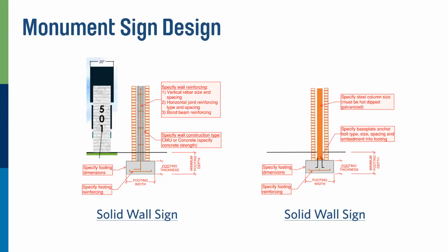Here in Georgia, or in the Atlanta area where we live, that footing is required to be a minimum of 12 inches below the finished grade, below the ground. The reason is frost. We do have winters and it does freeze. If you put that footing up high and it freezes, what happens to water when it freezes? It expands.